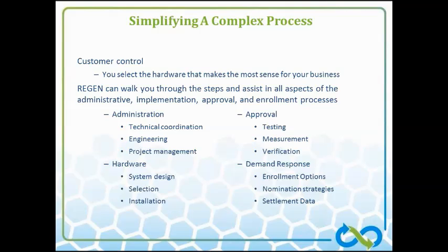Nomination strategies as far as figuring out, hey, I don't know how much load I can actually reduce for a demand response event. I think I can reduce my HVAC set points to 75 degrees, 76 degrees, but that's all I can do. We can help you to determine what that actually means on a kW level to help you nominate into those programs.